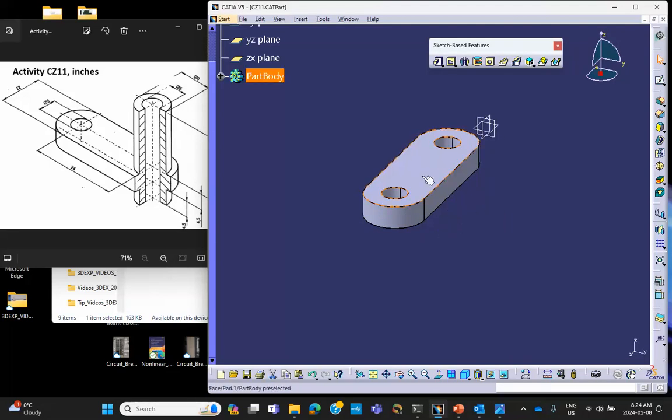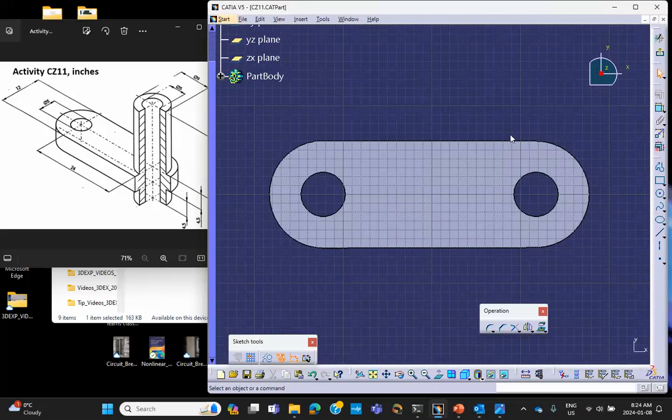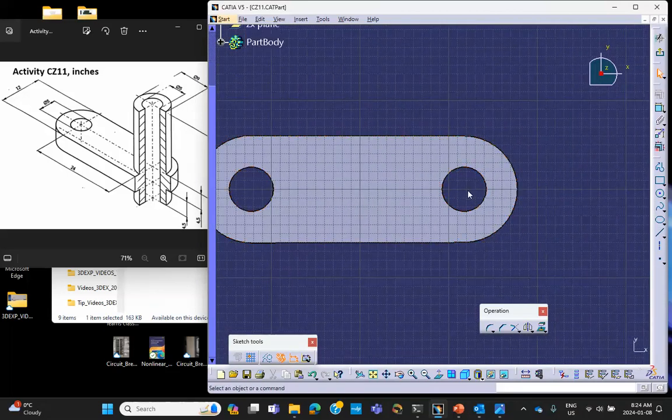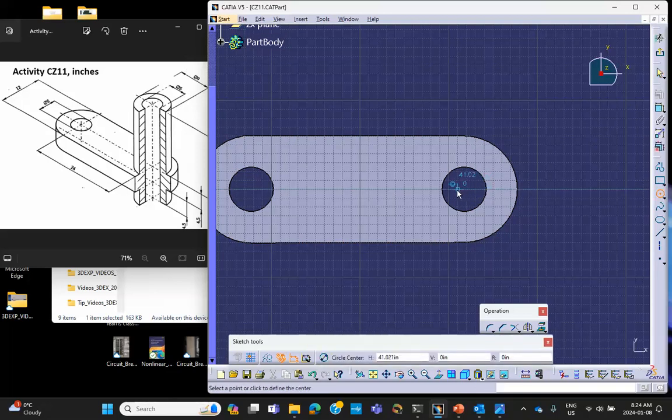So for example, on that face, by the way, let me click on the floppy so that we save everything. On that face, I will sketch. Okay. So what I'm going to do is draw a circle like this and another circle with a radius of 4.5. So let me draw two circles. On purpose, I'm going to draw it like this. And another one, 4.5.